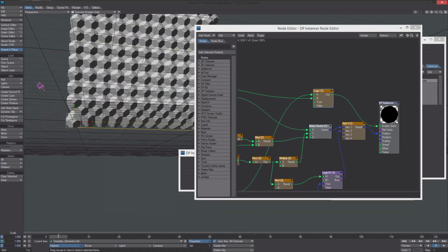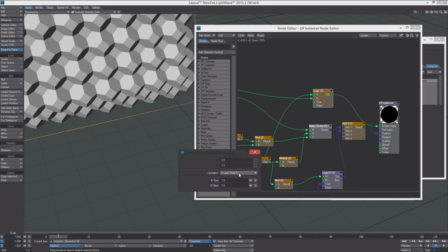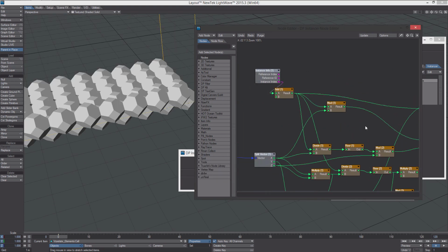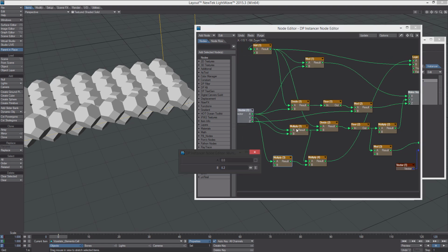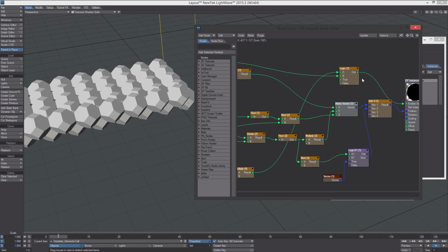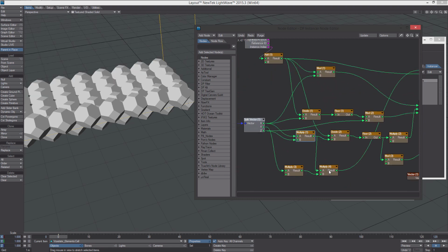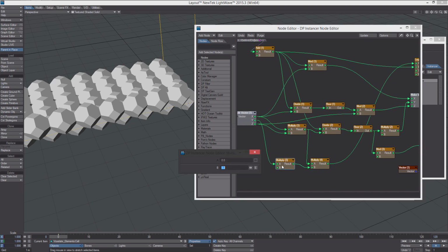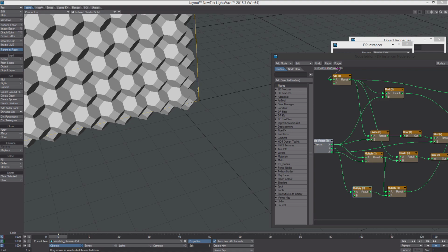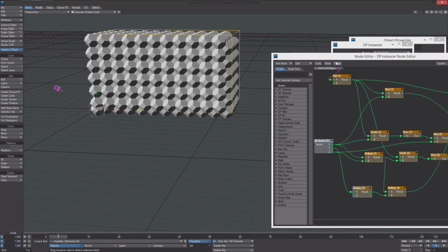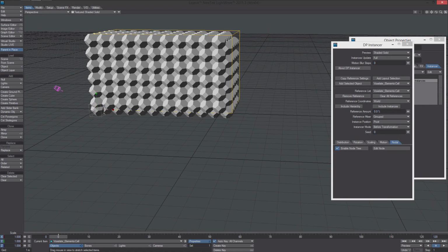Now I messed up there because I'm only scaling it by 0.2. That's why you can see it's broken. So we're just taking the X times the Y times 2 times Z. And we're saying if that amount is greater than the index, then we'll have it equal 1. And if not, we'll have it equal 0. See, now I'm realizing that I didn't have to multiply by 0.2. So now it works out. It was just that multiply had 0.2 instead of 2.